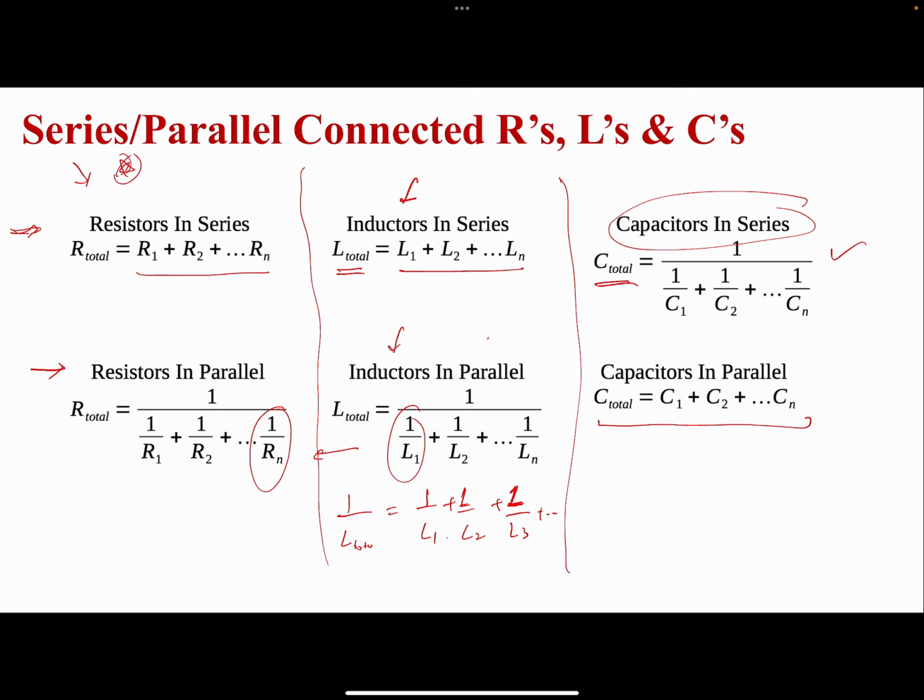So with that, we are going to finish this lecture. Some of the take-home messages of this lecture, right? An inductor is just a coil. You apply current to it, which produces a magnetic field. The changes in the current produce changes in the magnetic field. By Ampere's law and by Faraday's law, there is an induced voltage, right? And so the voltage can only be induced once there are changes in the current. So if there are no changes in the current, once the current reaches a steady value, the voltage across the inductor becomes zero, and it becomes a short circuit.